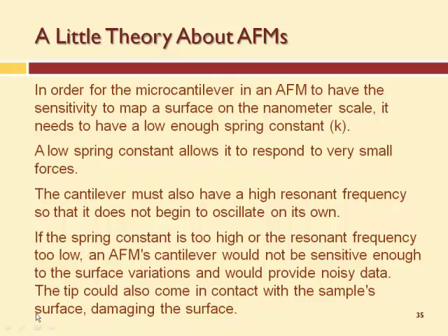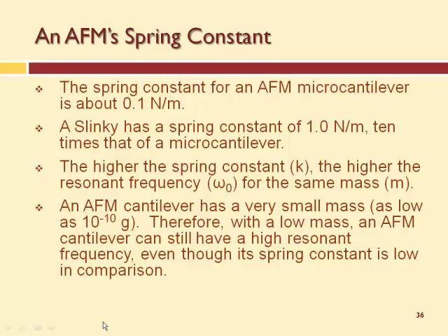So you have these structures, these dimensions to play with, as well as the material. Okay? So a spring constant on an AFM is about 1/10 of a Newton per meter. A slinky is about 1 Newton per meter, 10 times that. Okay, the higher the spring constant, the higher the frequency for the same mass. Atomic force microscope cantilevers have a very low mass. So with the low mass, it has a high resonant frequency, even though its spring constant is low. Okay? Does that make sense?